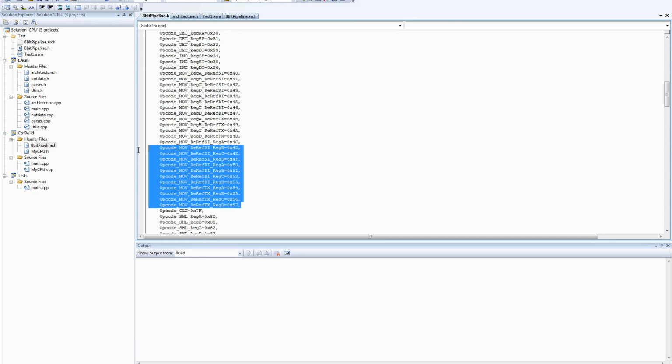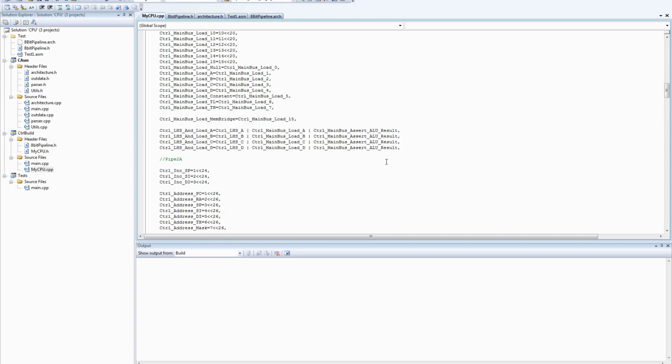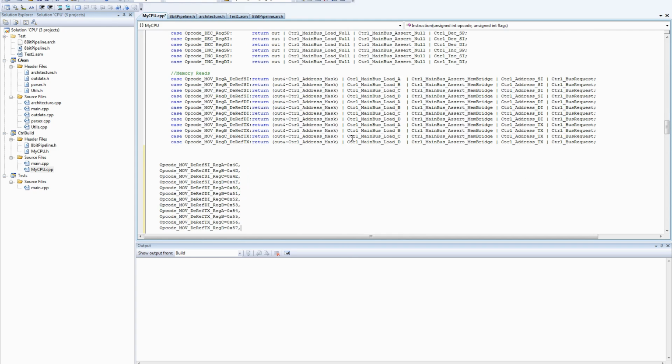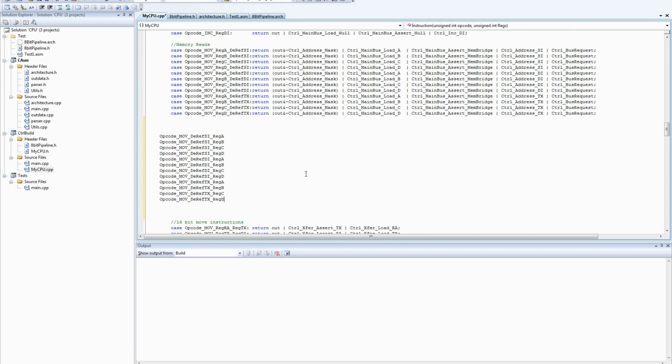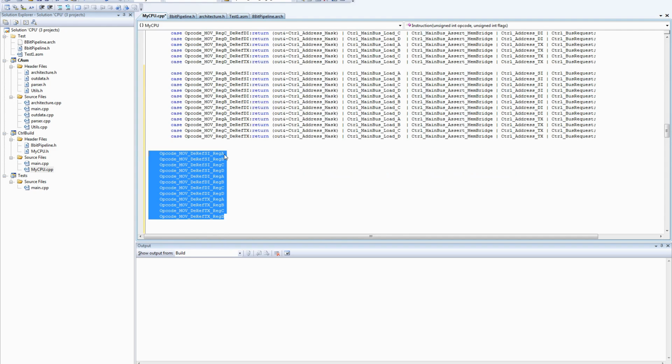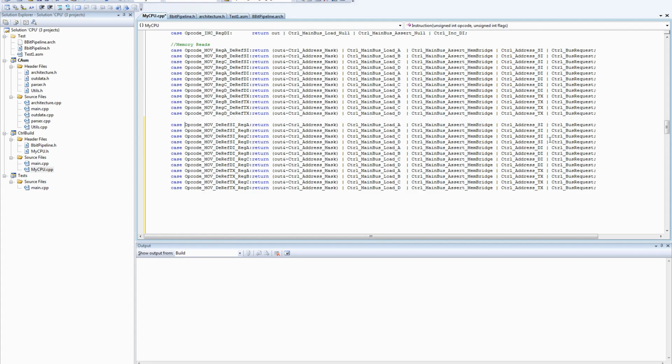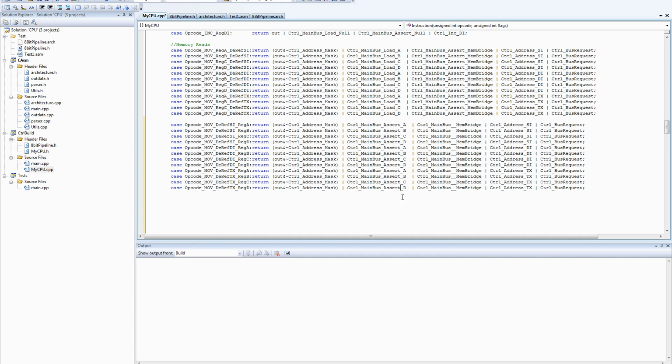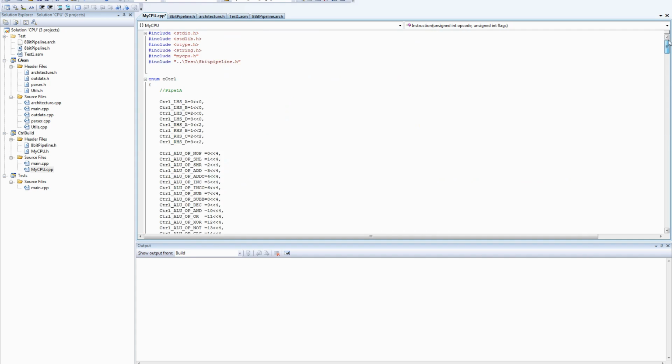So now we need to add the memory writes in. These are going to be very close to a copy of the memory reads. So the address we're outputting is the same. We want to assert the relevant registers and load from the mem bridge.